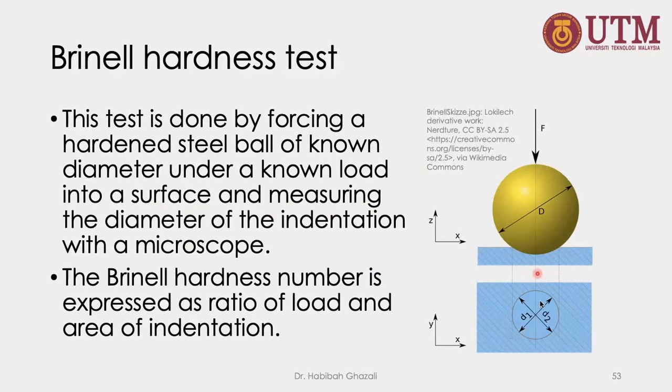But for the Brinell hardness test, we look at the shape of the penetration. Okay, the larger the area penetrated by this indenter, the softer the material. We measure the deformed area with a microscope and determine the value, how large the indented area is.